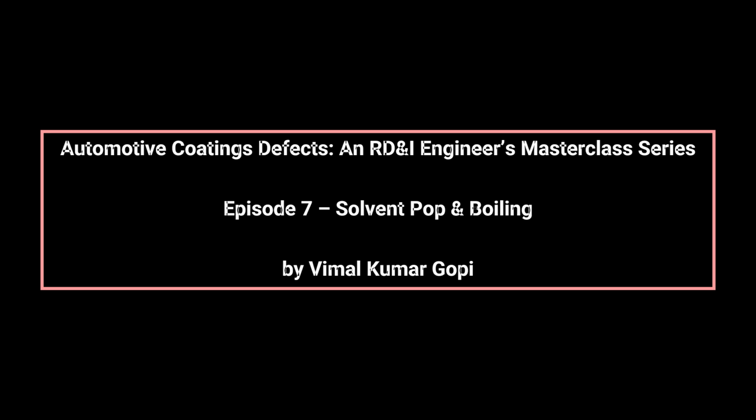The key takeaway is that solvent pop is not a mystery defect. It is a pressure relief failure caused by poor solvent escape timing. Control solvent evaporation, keep the film open long enough, and manage thermal input correctly, and the defect disappears entirely.